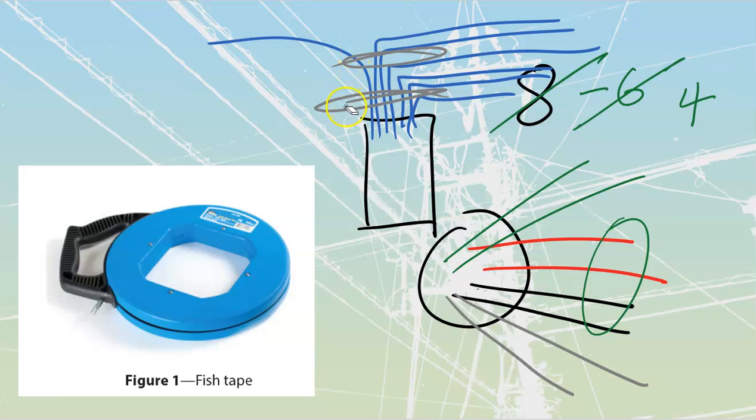The length that you bundle these cables together is going to determine whether or not you need to derate. We have to watch that length when we're bringing these things together, because if you go past that, and trust me, the inspectors know all about this and they will not hesitate to bust you on that, you're going to run yourself into issues where you have to start derating. We don't want to have to derate all of our Loomex, if at all possible.